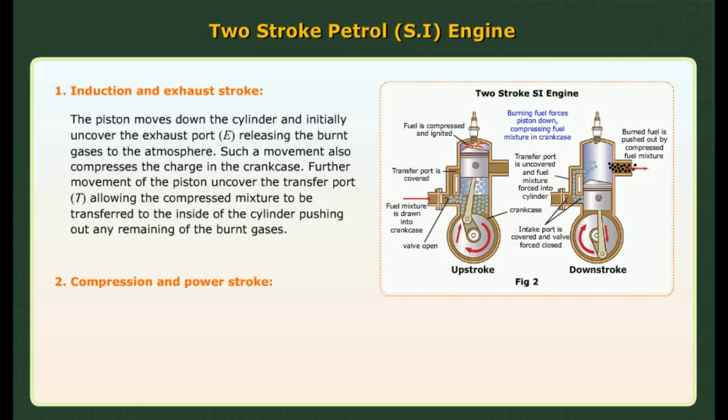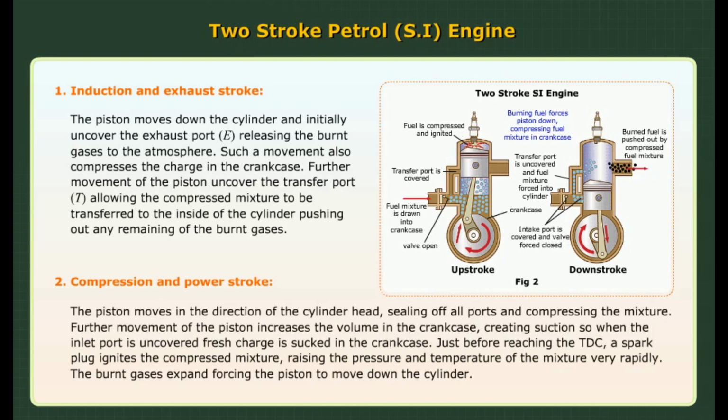2. Compression and power stroke. The piston moves in the direction of the cylinder head, sealing off all ports and compressing the mixture. Further movement of the piston increases the volume in the crankcase, creating suction. So when the inlet port is uncovered, fresh charge is sucked into the crankcase. Just before reaching the TDC, a spark plug ignites the compressed mixture, raising the pressure and temperature of the mixture very rapidly. The burnt gases expand, forcing the piston to move down the cylinder.